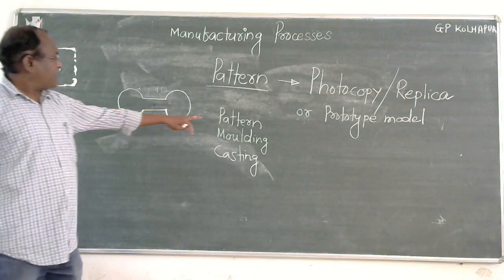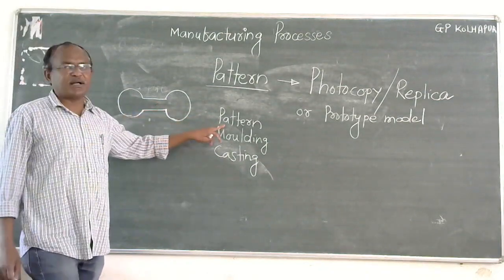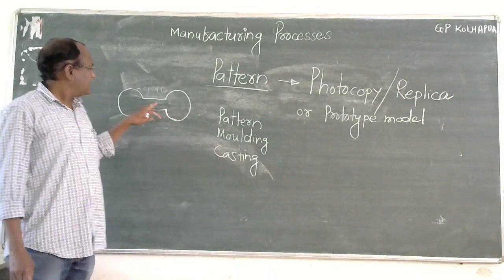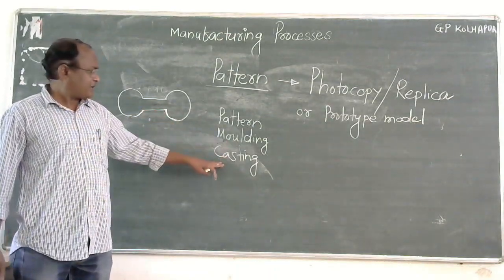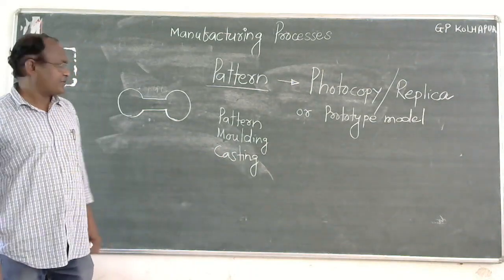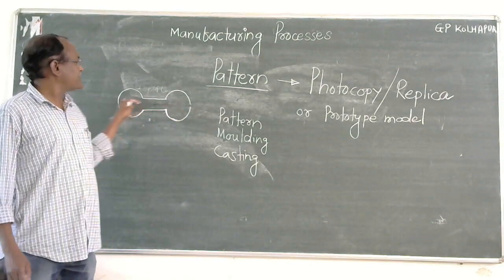First prepare the model of this dumbbell, that is called a pattern. Then go for the molding process, sand molding process, then go for the casting process.